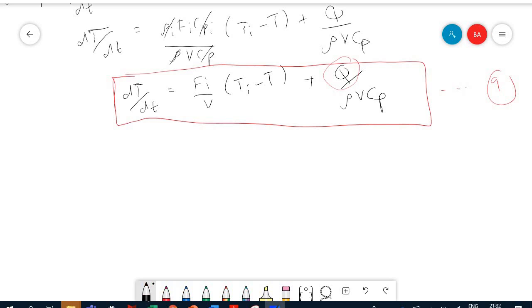And Q, in this case, where we had our system of a CSTR. Okay, so this is our system, and we had a cooling or a heating process. Considering that the system, for example, has an exothermic reaction, we said that if it's exothermic, what do you need? You need this blue thing, cooling.